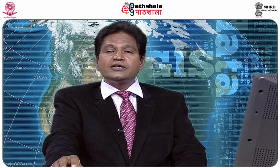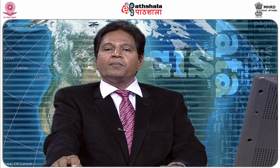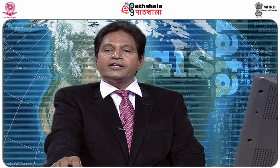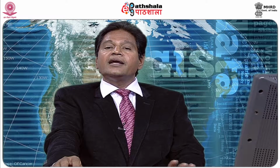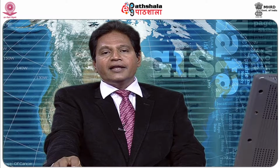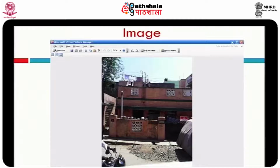In fact, this last slide which I showed you gives you an idea about the number of floors in a house. Because when I am working in GIS, as I was just telling you, when I see from the top, satellite data will give only the plinth or the topmost portion of the house. When I want to know the number of floors, I have to go to the field. So, when I go to the field and take a photograph, I need not depend upon my surveyor or whoever it is for that matter, and that detail can be obtained by a photograph. By linking the photograph to my GIS database, I will also know how many floors there are. If I know the number of floors, I can calculate the area of the house from the top part of it. So, this is one simple application in GIS, hot link, linking objects.